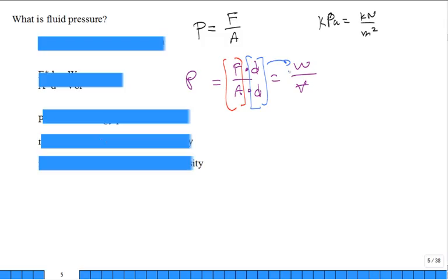But it's organized energy transfer. And then what do I have here? The volume. So when you see pressure, right away you can say, aha, pressure is the force per unit area. But it also can be interpreted, especially in a flowing fluid situation, as some sort of energy per unit volume. Mechanical energy per unit volume.